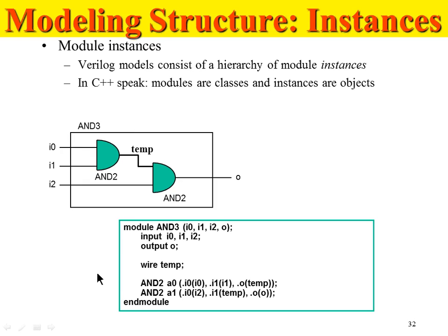Any questions on this, how it is working? Nope. So this way of modeling is called structural modeling. We saw that using Verilog there are two methods, the structural modeling method and the behavioral modeling method. Structural modeling means we are literally creating this structure using the Verilog language. So this will be part of structural modeling. We can create even bigger designs out of it as required. Using smaller designs, we can create bigger designs.